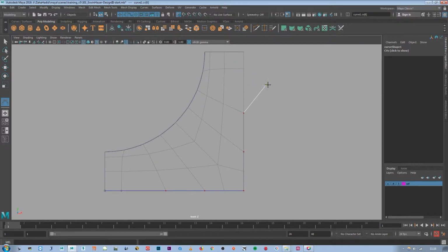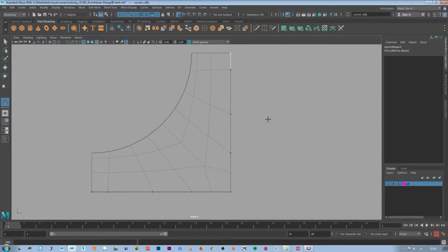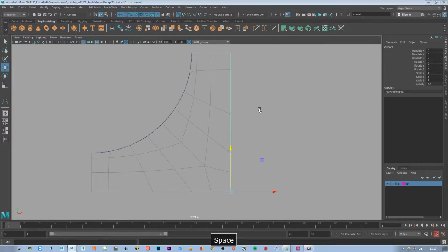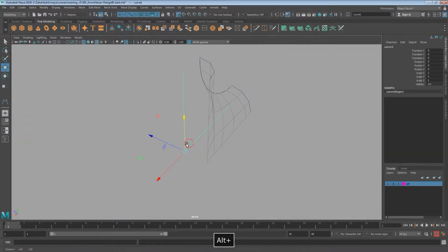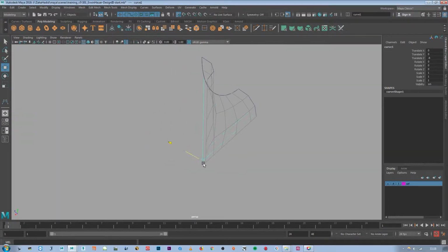You can also click and drag until you find the point you want, so it's like a rubber band. And when we're happy with that, press enter on the keyboard to drop the curve. Perspective. It's just spacebar and drag up as perspective view. And then we'll move that into position. In this case it's -7 in Z. So now they're all lining up.